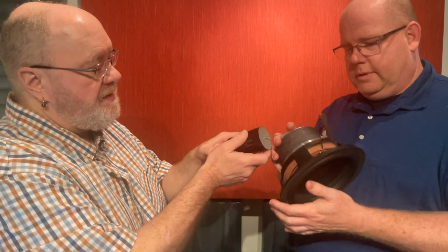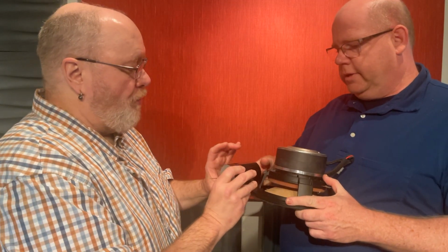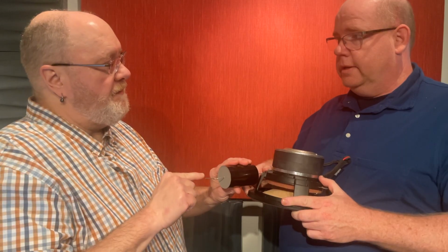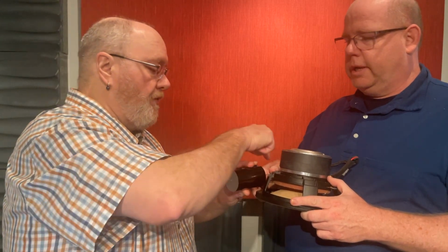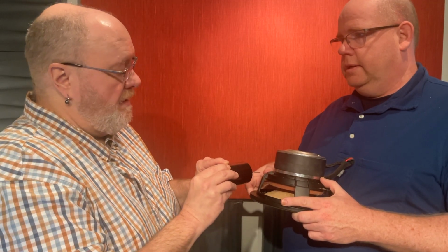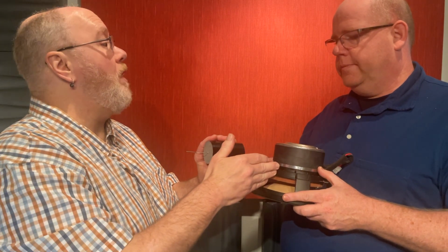If you put it on the positive, we'll call this one positive and negative. You put it in series. When I say series, that means it breaks the connection between the positive wire getting to the driver. So positive here, and then it goes through. So that filters low frequency information, and you use the microfarad rating of the capacitor in relation to the impedance of the driver to know at what frequency that starts.